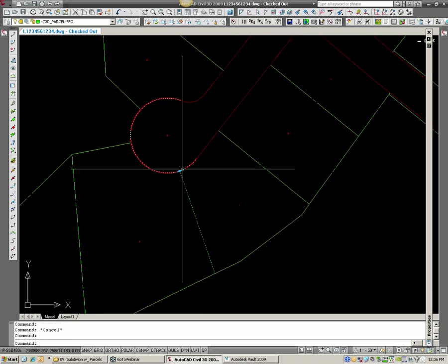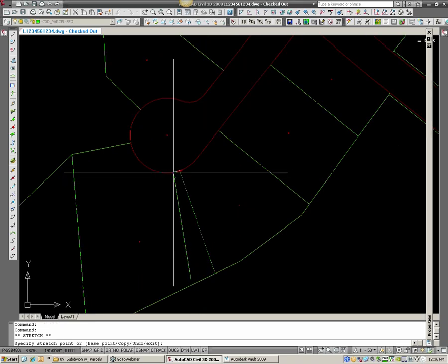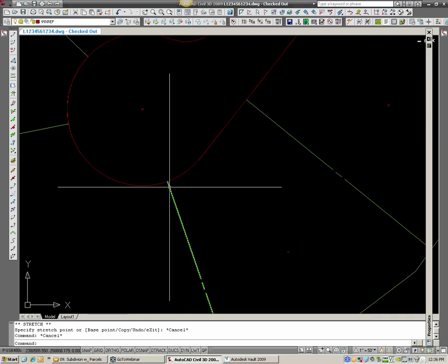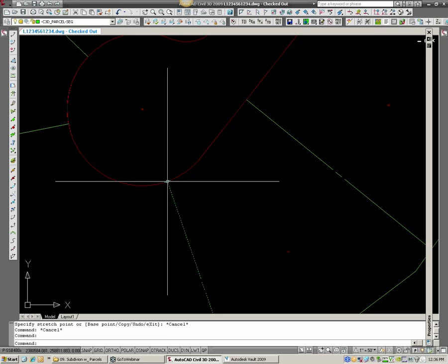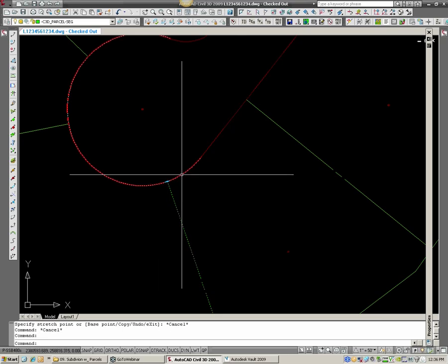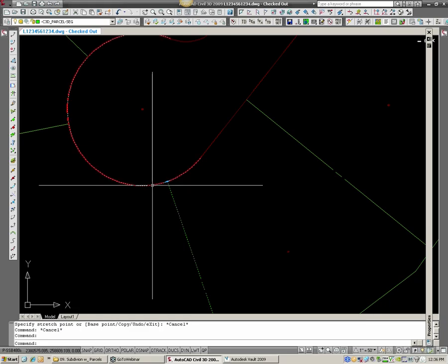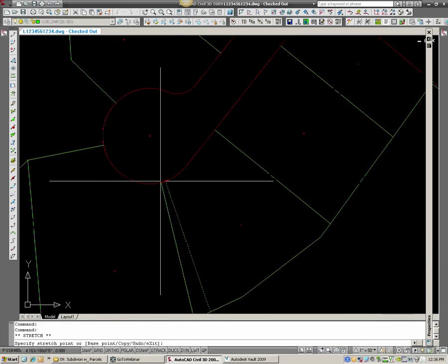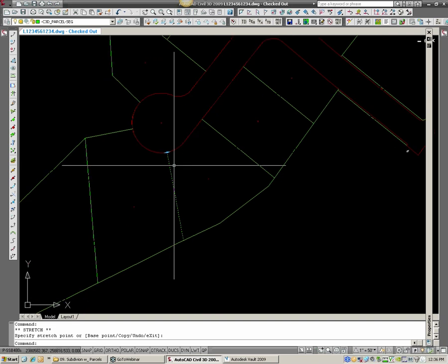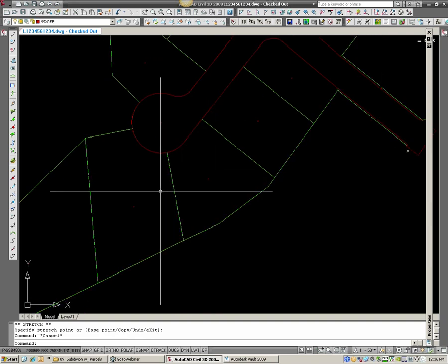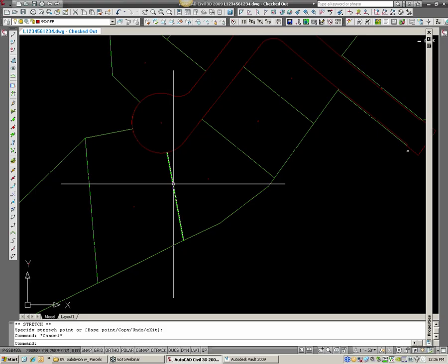So what I can do with this now is it gives me a little bit better editing tools. I can actually grab this line and say I wanted to increase his frontage by 20 feet. Otherwise I'd have to measure across here, maybe in the future after a submission or two, and just get a line that's 20 feet longer. You're going to draw a 20-foot arc. And then I can just drag this line over and snap it, and it will automatically extend out to this back parcel line, and both parcels on either side will update automatically.